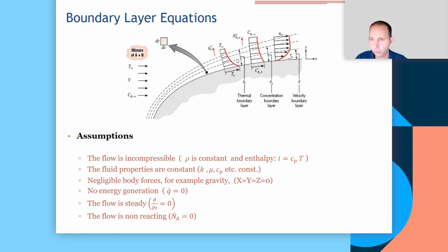The flow will detach from the surface, and in an attempt to reconnect with it will create large vortices that are very unstable, that is, they change over time and space, and that means you can't really simplify the governing equations in any way. All three components of velocity as well as time need to be resolved, and that means that you're dealing with a very complex problem.